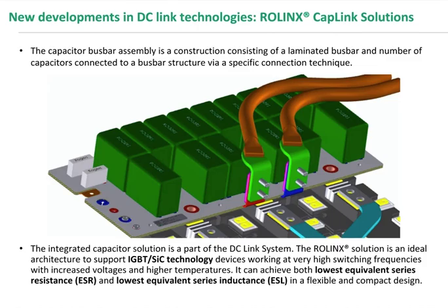So in terms of new development within Rogers and Rawlings, we have already been offering on the market for more than 3 years capacitor busbar assembly solutions with different types of capacitors. Right now we have our own solution where, as you see in this picture, we have laminated busbars, and on the busbars we have integrated capacitors.